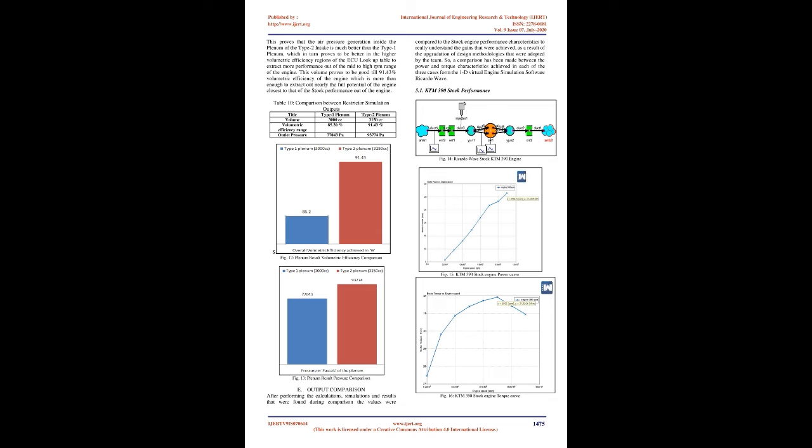Formula used: D equals 154 x number of cylinders x stroke x bore² x max power RPM x 1/267,547, where stroke equals 60 mm, bore equals 89 mm, max power RPM equals 9000 RPM. D equals throttle body diameter. So, the required diameter of the throttle body outlet equals 25 mm.